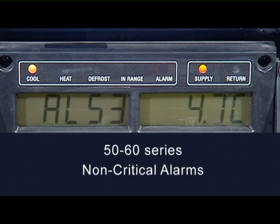When a 50 and 60 series alarm is activated, the alarm code will flash alternately with set point when active. When a 50 and 60 series alarm is active, the unit will continue to run and maintain the set point temperature. The alarm light will not be illuminated for these alarms.